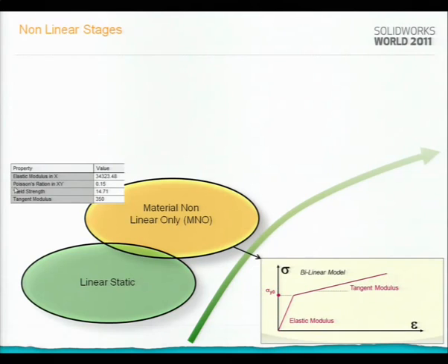We have elastic modulus, Poisson's ratio, yield strength or yield stress, and the tangent modulus. This is a bilinear model, right? Many of you can ask, okay, but Jose, I want to get the whole curve in my nonlinear analysis. It could be done, but in many cases it is not necessary, because a bilinear model is faster, and I get the same result.